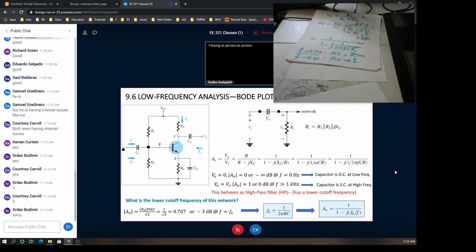When the frequency of this signal is 0, DC, like the 10 volt input we have here that has a frequency 0, the capacitor will appear like an open circuit. There is no current. The output will be blocked, right? Because of this open circuit. The output voltage would read 0 volt. There is nothing at the output.